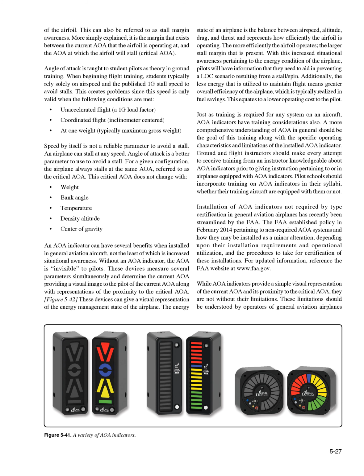The energy state of an airplane is the balance between airspeed, altitude, drag, and thrust, and represents how efficiently the airfoil is operating. The more efficiently the airfoil operates, the larger the stall margin that is present. With this increased situational awareness pertaining to the energy condition of the airplane, pilots will have information that they need to aid in preventing a LOC scenario resulting from a stall/spin. Additionally, the less energy that is utilized to maintain flight means greater overall efficiency of the airplane, which is typically realized in fuel savings. This equates to a lower operating cost to the pilot.